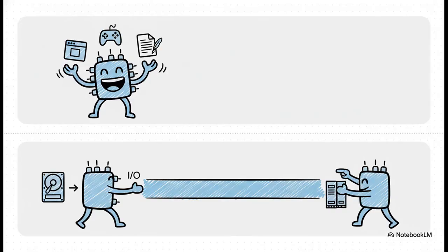And here's the real magic, the core benefit. The DMA module takes complete control, and it transfers the entire block of data directly between the device and memory. It completely bypasses the CPU. So while the DMA is busy being a data mover, the CPU is free to go execute another program. They're working in parallel. This is true multitasking, right at the hardware level.